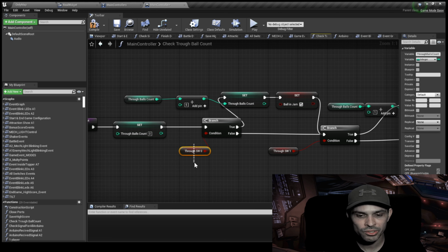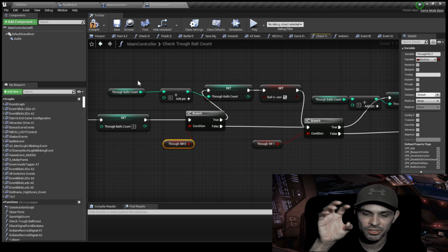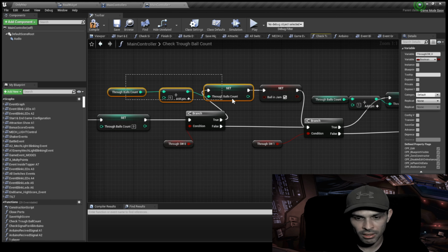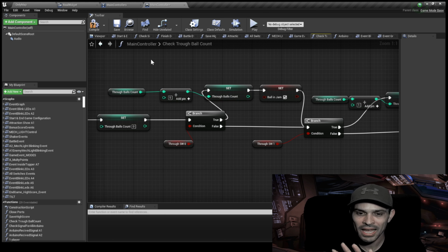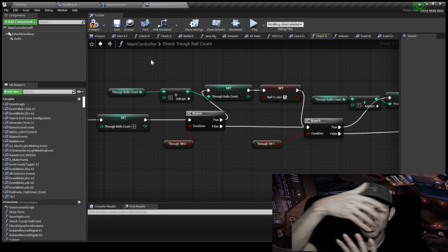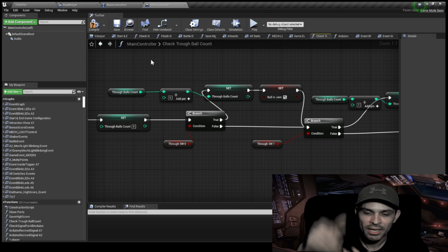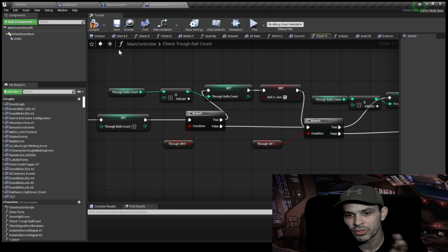So if switch 0 is off, continue, which is the jam. Remember, 0 is jam. And I got a simple add-on here because I got 4 balls only. If I have a jam, if a ball is on top of another one, this is a jam. Sometimes the switches are not pressed correctly. So that's why I say, if you have a ball there, just add 5 balls, and now I know for sure it's a jam, and I will punch those balls out, and then I'm going to read the count again. That's another piece of the coding that I have.